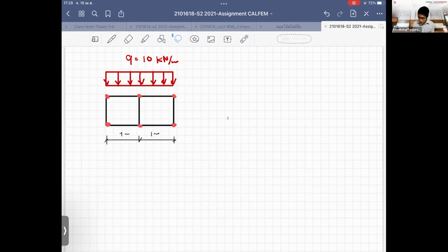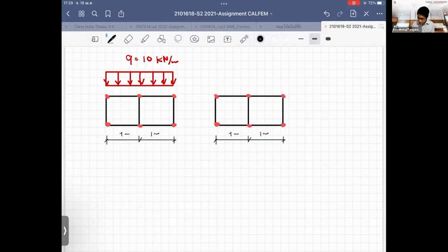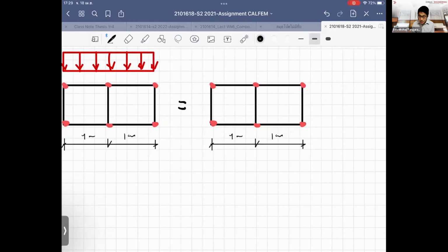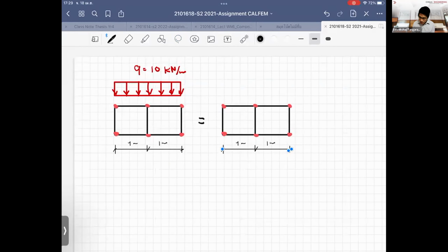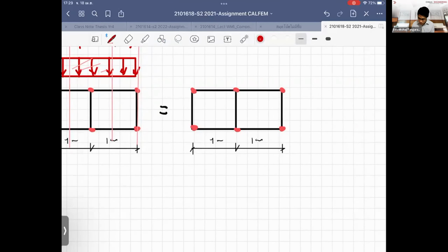I don't think you need the integration using the shape function, because it is bilinear anyway. So if you have a very simple case like this, you just use a tributary area concept and subdivide the loading according to the areas, the length that is covered. For example, in this way, it's covered according to this length and so on. So that's how you will have the force.